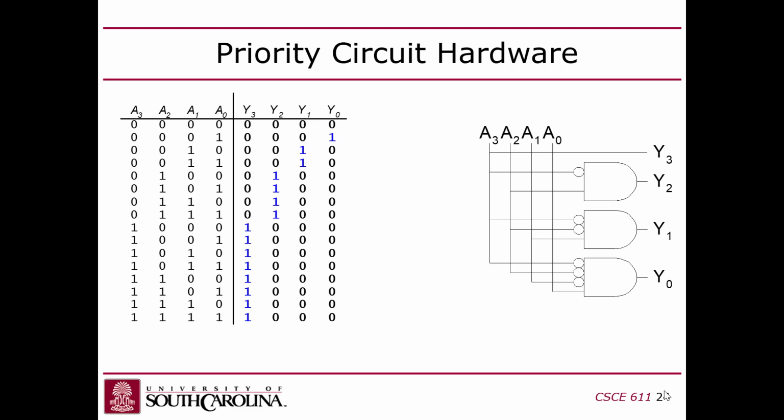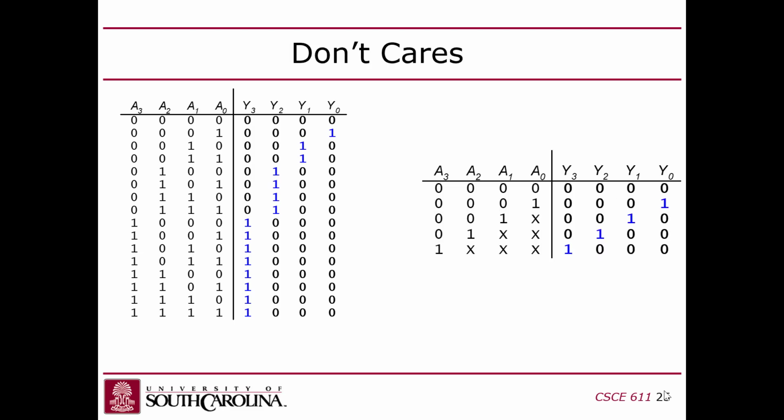So that means if you look at the truth table, we're dealing with these 4 rows, and in these 4 rows, you have a 0, 1 for A3 and A2, right? Now you might say, well, wait a minute, that's like a minimized version, because these are not max terms, or this is not a canonical form at all, right? But the way this was constructed was by using don't care. So a don't care can either be in the input or the output.